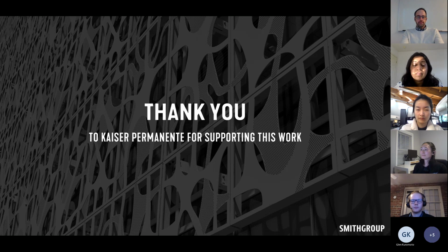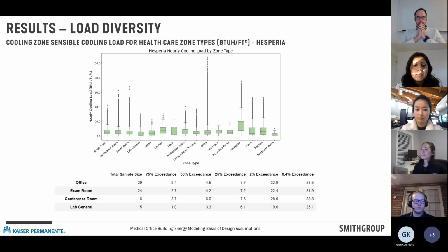The big thing I wanted to know is, did we validate the loads that you had published before, like cooling loads 20 BTUs a square foot, heating 10 BTUs a square foot? Yeah, actually, I wrote that down. Eli had 2 slides in here, slides 41 and 42, that are some really good updates to that sort of famous table that we published out of the last study.